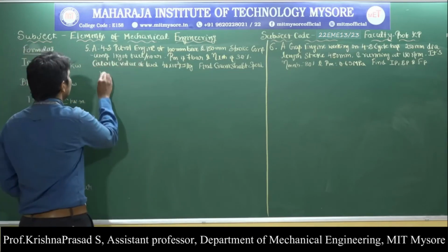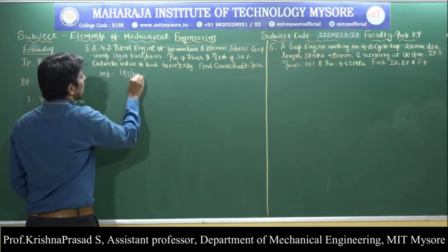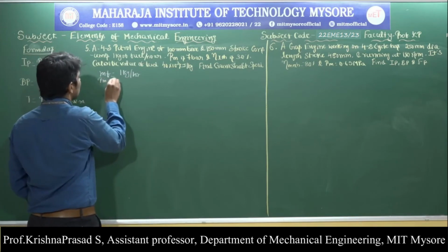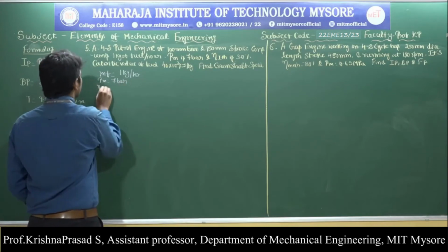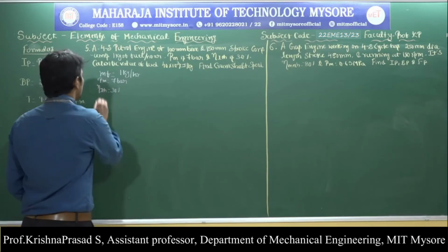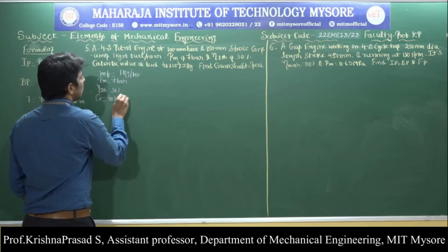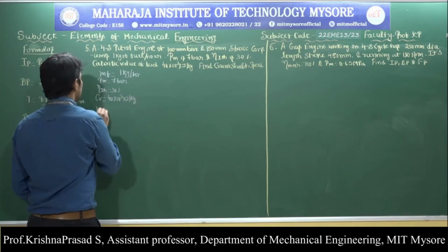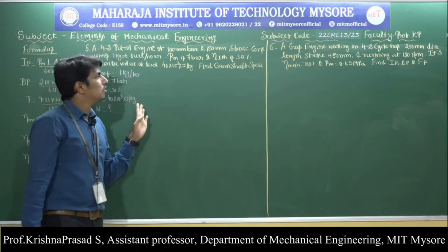That is MF equal to 1 kg per hour, and PM is 7 bar, and indicated thermal efficiency is 30%. They have also given the calorific value, which is 40 into 10 to the power of 3 kilojoule per kg. So find the crankshaft speed. We know that this is a 4-stroke petrol engine.